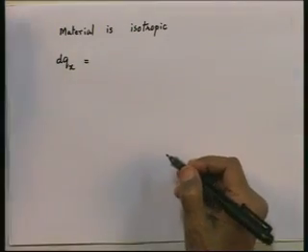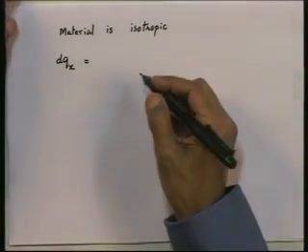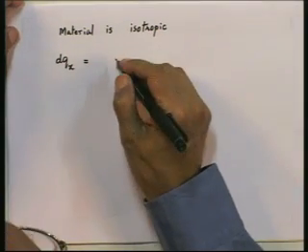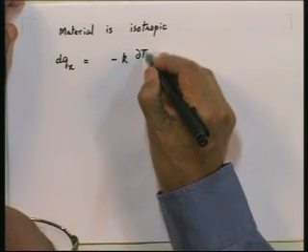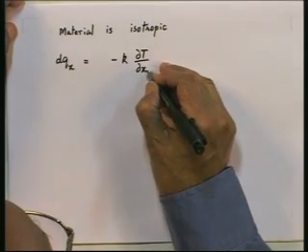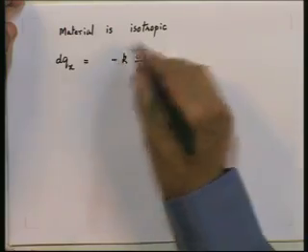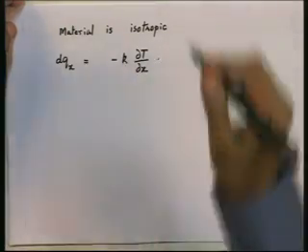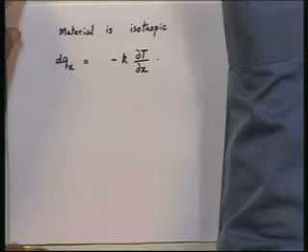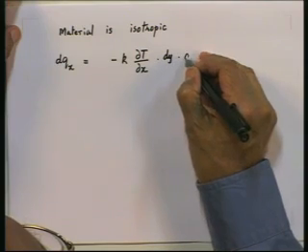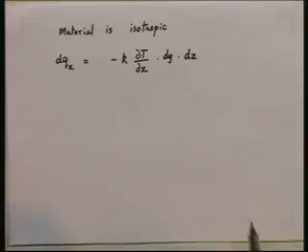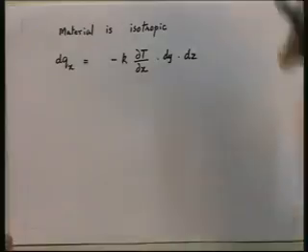By Fourier's law of heat conduction, dqx will be equal to minus k dT/dx, this is the heat flux in the positive x direction, multiplied by, since we want the rate at which heat flows, the area of that face, which will be dy dz. So many watts is the rate at which heat flows into this x face.